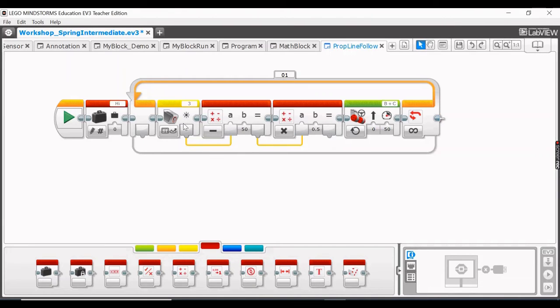So let's go back to our 100 example. Our light sensor is on white. It gets 50 back because it's subtracting the threshold value, or our target value almost. Then it puts that into this scaling block, and this scaling block puts out an output of 50 times 0.5, which is 25, which can now go into our steering, therefore resulting from a value of 100 going to 25.